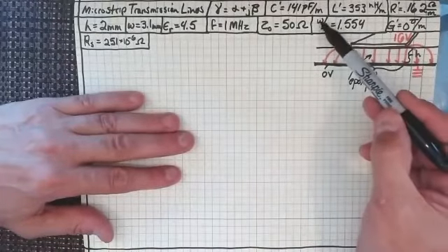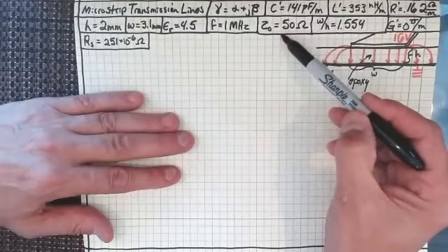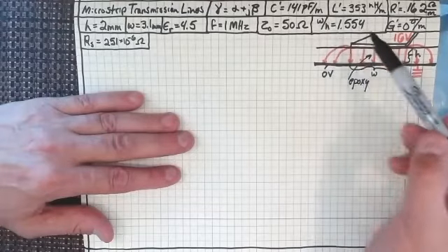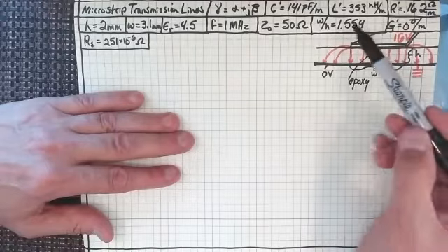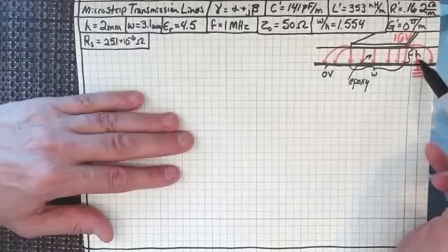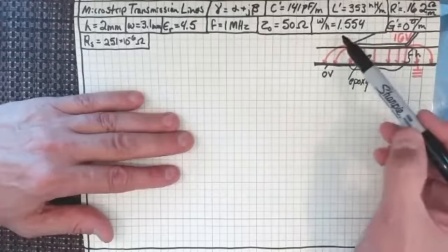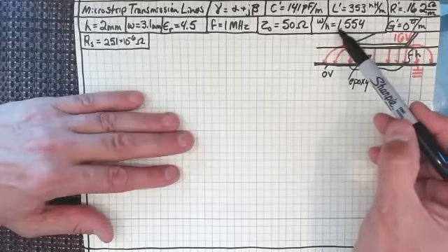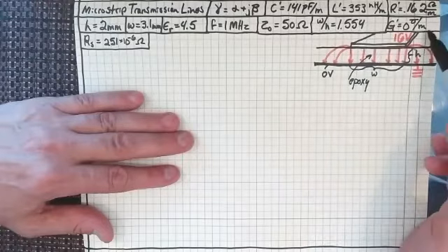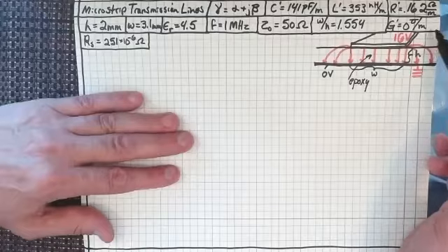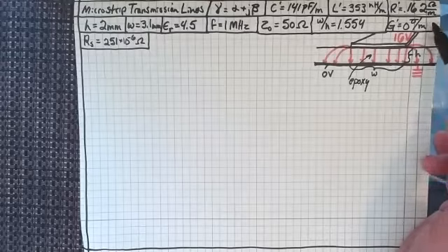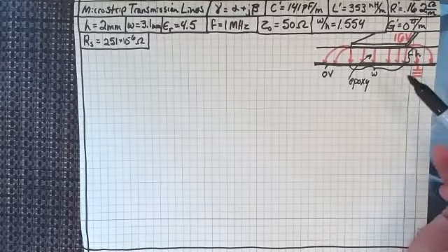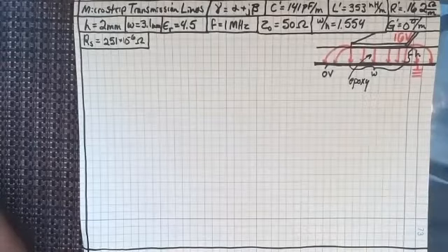Because we have a 50 ohm connection, we figured out that the ratio of the width of the printed circuit board trace to the thickness of the epoxy printed circuit board had to be 1.554. And we're still making the assumption, like we do in all undergraduate courses on electromagnetics and propagation theory, that G prime is pretty much 0. You could say that because epoxy is a great insulator, as well as being a good dielectric.